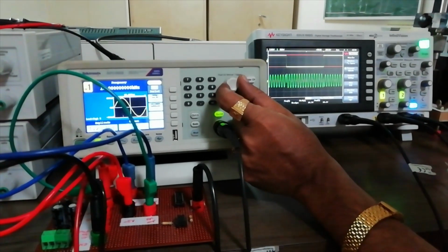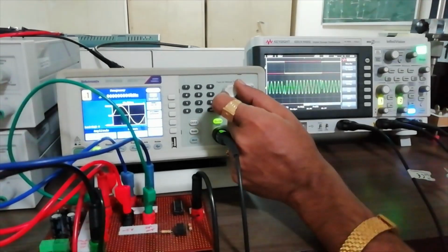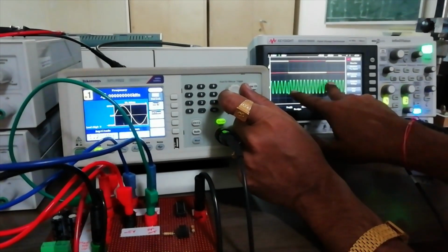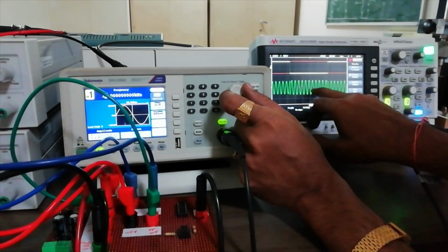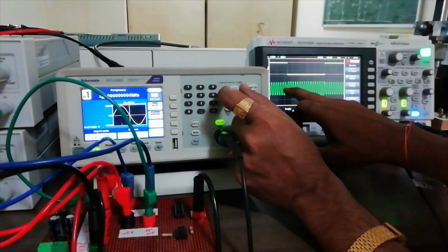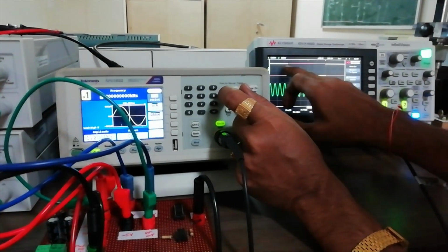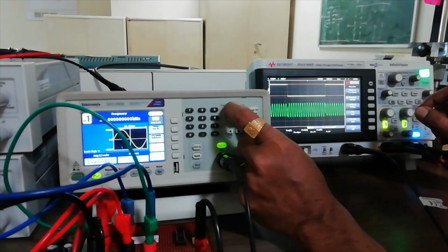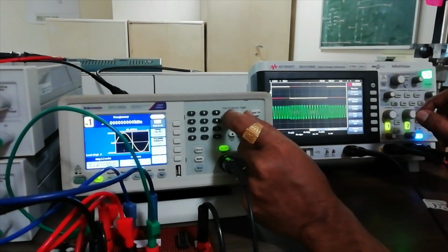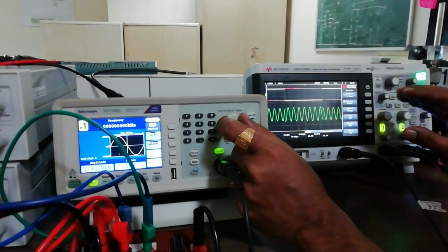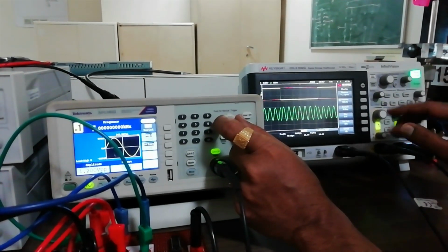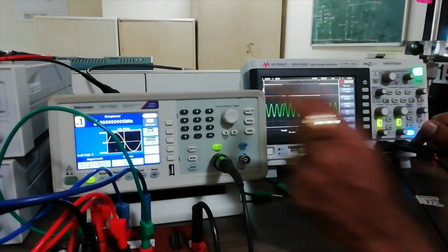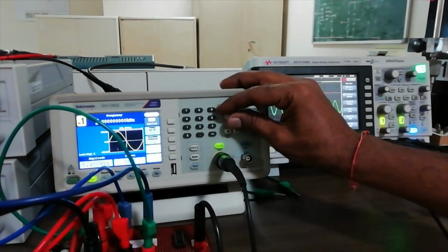It does not require any change in terms of frequency. So it corresponds to phase, corresponding to logic data, whether the frequency is less or more. So the carrier is constant in terms of magnitude and frequency, only phase changes are there. So it's phase shift keying.